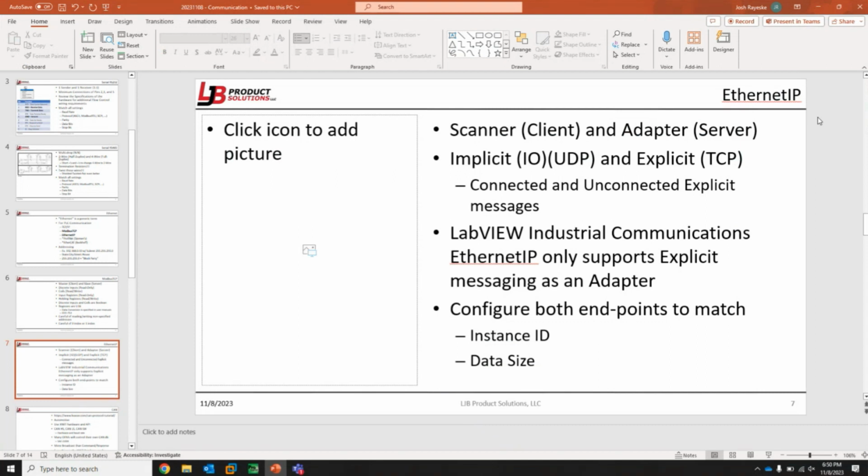You buy one of these little CPUs. There's plenty of gateways out there that'll do Ethernet IP to whatever you want. I know there's a company that pops up on my Google search, Real-Time Automation, I want to say, in Pewaukee. They have gateways for anything to anything, basically. You just tell them what you need and they configure it to do it. But it's probably going to cost more than that little CPU, which is $280 maybe. And not only does it give you the Ethernet IP scanner and the ModbusTCP stuff, but it's a programmable logic controller. Put anything on there that you want.